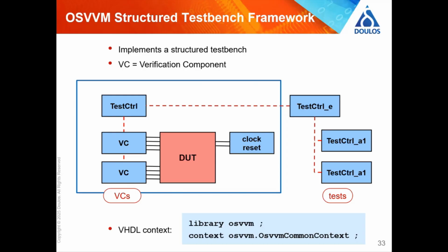So OSVVM now has a structured test bench. So we've got verification components, one per interface of our device. We've got test controllers, clock and reset logic, and there's quite a lot of built-in IP now in the OSVVM environment to enable you to build these things very quickly.